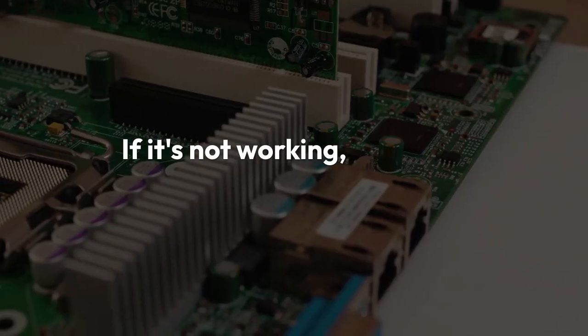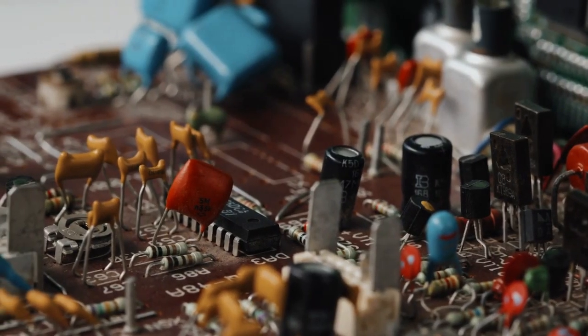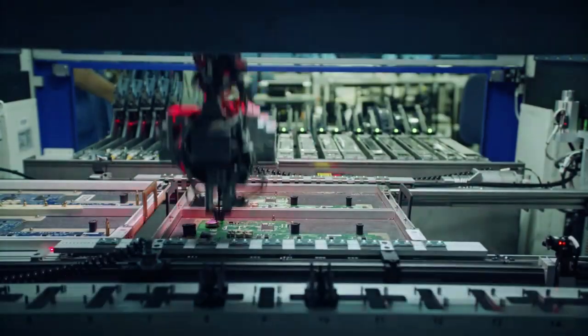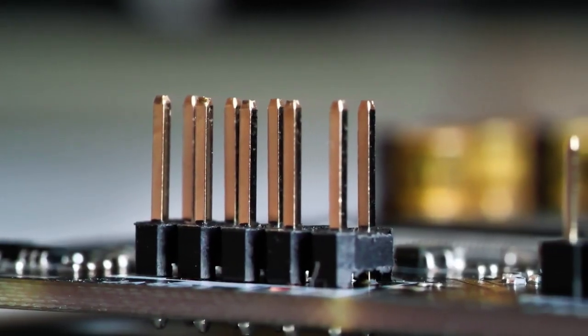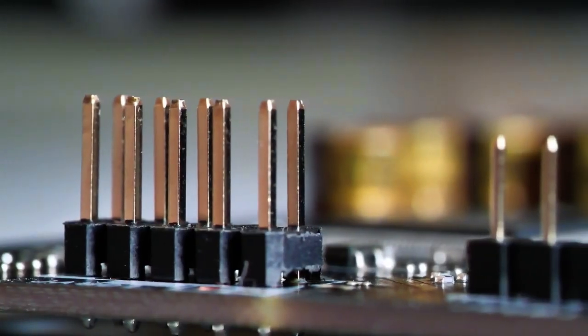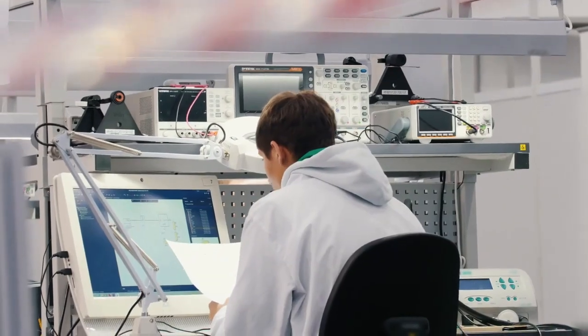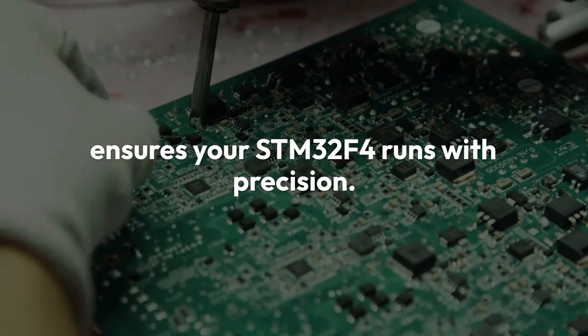If it's not working, carefully double-check everything. Verify your crystal part number and its specifications. Confirm the capacitor values are correct. Review your PCB layout for any issues. Also, make sure your STM32F4's RCC, reset and clock control, registers are correctly configured in your firmware to enable the high-speed external, HSE, oscillator. A properly designed and laid out crystal oscillator ensures your STM32F4 runs with precision.